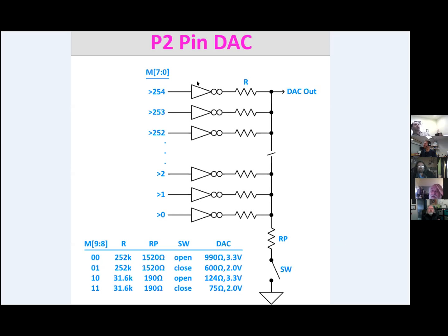You mean to say that there are actually 254 resistors feeding an output? There's the equivalent of 255, yes, but they're grouped. We have a 16-size resistor, and that's controlled by a single thermometer bit of logic. So we have 15 groups of 16 which are treated as one. Aha, I see. And then we have an 8, 4, 2, and a 1 equivalent as well.